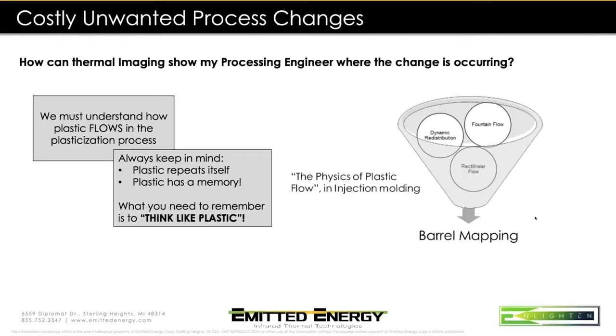There are things you got to keep in mind: plastic will always repeat itself. Plastic has a memory. And plastic will also come from one area and map itself from one to another and repeat itself from one area of the material path to the other.